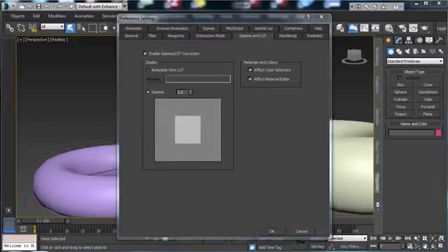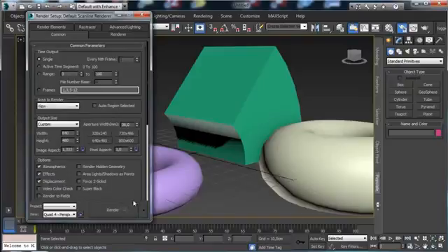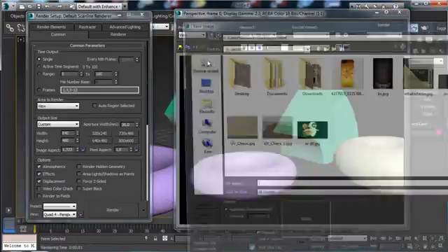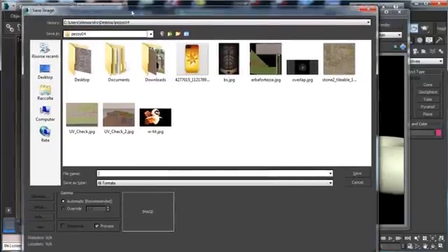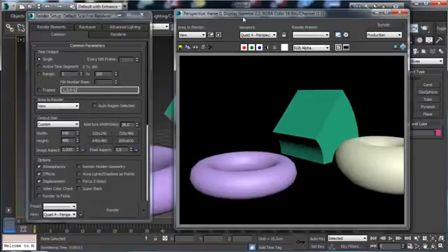So everything is done automatically, and also when you are trying to save an image, so let's go there and say we save an image, you see that there it is still set in a different way. We have the automatic and we have the override where we can put the gamma. In this case the gamma is manipulated manually or automatically, and when it is automatic, 3ds Max is managing it in the right way with a 2.2 gamma correction.